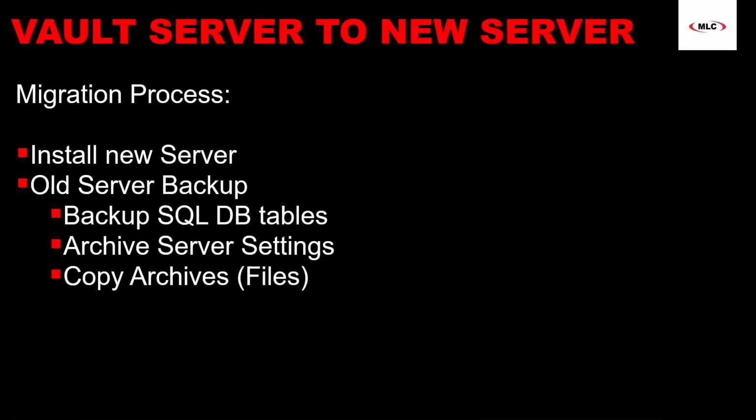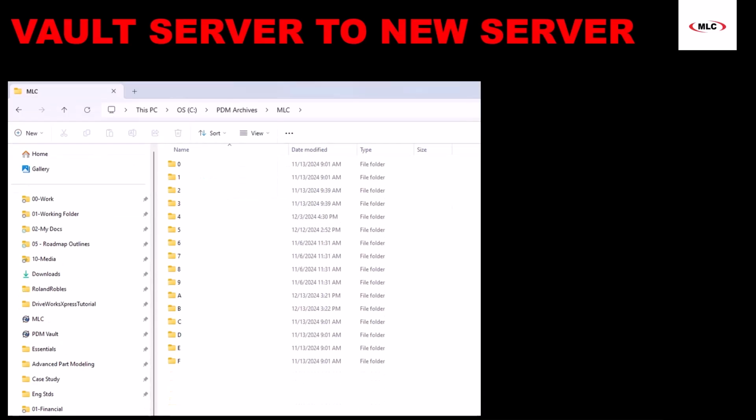The last thing is copying the archives, which again is just a fancy way of saying the physical files. So on the server, you're going to see an archive location. Again, kind of mirroring that theme, this is not going to be a one-size-fits-all. I would not physically know where your archives are. That would have been dictated during that initial setup of PDM.